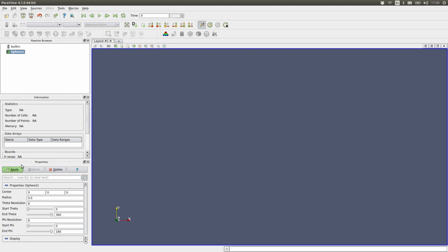The reason we do it like that is so that we can change some of these parameters, and that will quite often be the case, and you will need to do that with more and more care the larger your models are, because they will take a few minutes to load. There is an option here to use auto apply. By and large it's better to leave that off, except under some particular circumstances, so that you can set these parameters how you actually want to set them. The defaults are usually kind of sensible, but they're not always what you want.